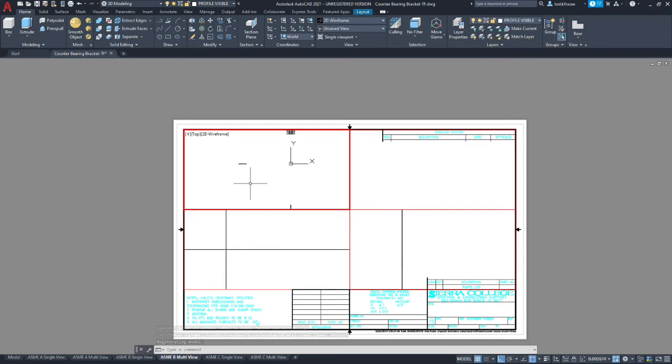So we can see that what we want is a top view towards the top of that frame. The 2 lines you see on either side are actually your other views, and that's why you want to draw them far apart. So let's go to the next viewport, and we're going to do the same thing. We can hit enter, and we're going to zoom, and we're going to go to extents.